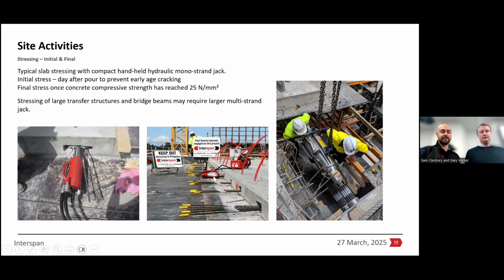Just another view there, and it gives you an appreciation for the pockets and the layout and where the grout tubes sit. So after the tendons have been stressed and the pockets cut and sealed, we can come along later when the deck's removed and there's edge protection on there. We can grout up the tendons from inboard of the slab edge. All the stressing's done inside the edge protection, whereas some old anchors had the grout tubes coming out at the face of the edge of the concrete, which wasn't ideal once the decks were struck.